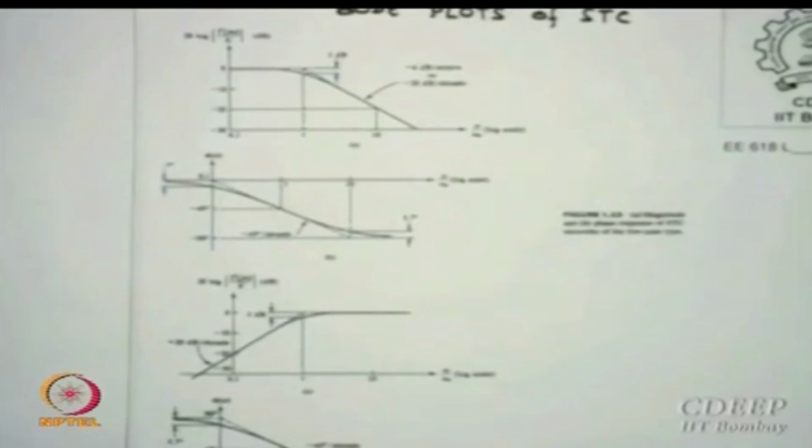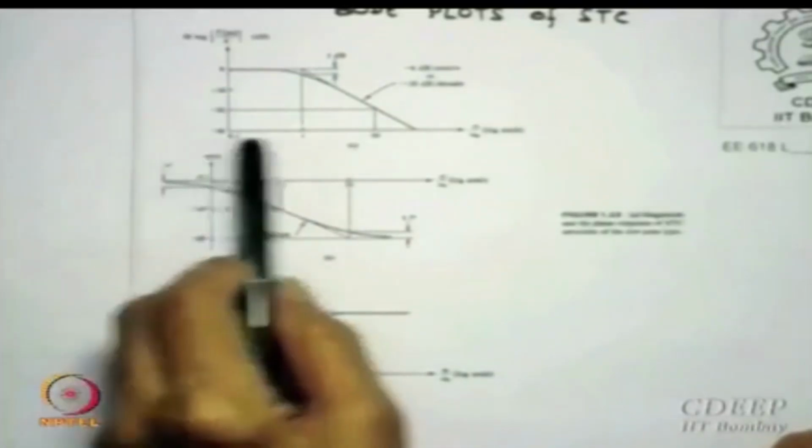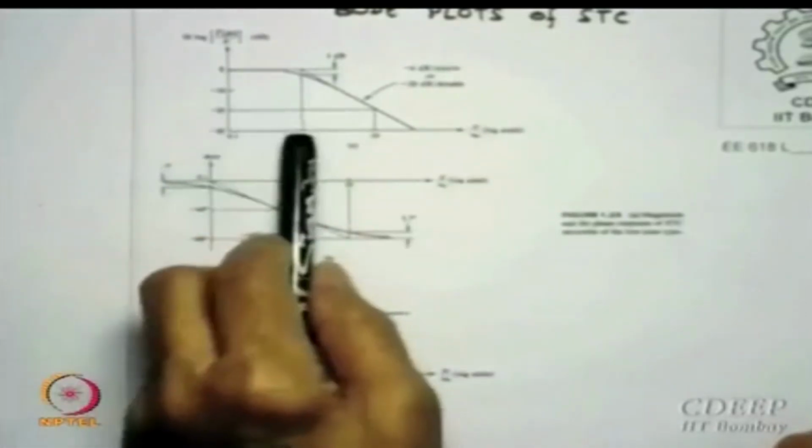and it is named Bode essentially for a simple reason that Bode was the very old control system man. Okay, and he had a book of 1948 called Feedback Control Systems. So if you read that book, fantastic. So what Bode did, essentially if you plot a gain versus frequency, and this is log scale, normalized gain T in dB by k, 20 log of that in dBs, and this is the frequency scale in tenths, that is decades.